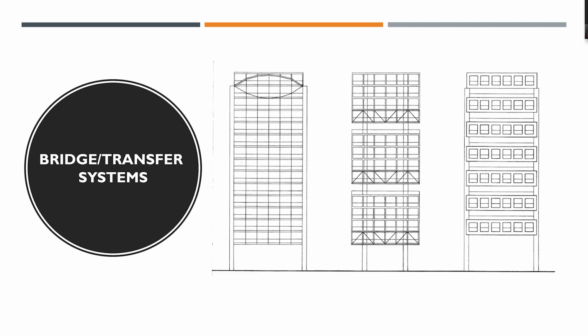As an alternate way to transfer, sometimes people just carry the load up rather than bringing it down, because down here you do not get the space to put the girder. So you take the load and you put an arch or a truss at the roof and carry the load back up, hang it from there rather than transfer it here. So it could be here, it could be intermediate.